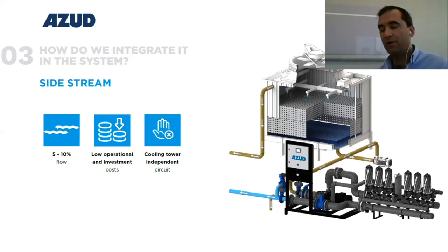Also, very important, you have a lower maintenance cost. Traditionally, cooling towers are cleaned by draining the tower and having the sediment removed either mechanically or manually from the sump. The costs associated with this cleaning process include downtime, labor, loss of water, and additional chemicals. So systems that are cleaned with a side stream filtration routinely provide longer periods of continuous operation before being taken offline for required maintenance.